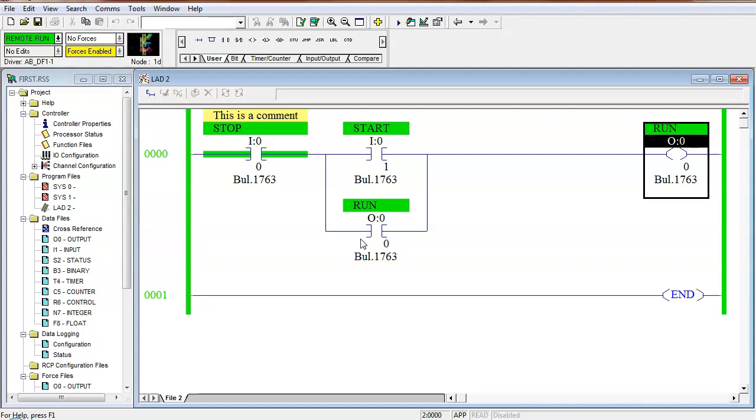I'll wire the circuit up, by the way, when y'all go on break. I'll actually wire it up to a motor and show y'all what happens if I use that other one. So all you have to do on switch one, which is supposed to be a momentary contact switch, is just take push button 1 or switch 1 and click it to the right and let it go. And it seals itself in.